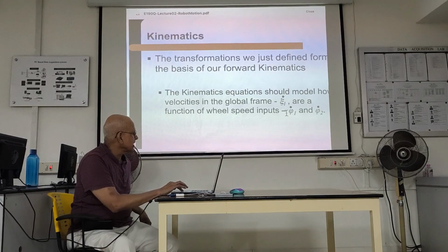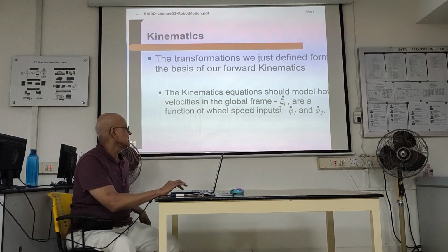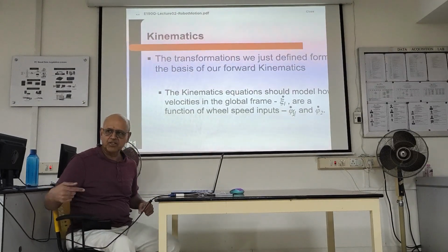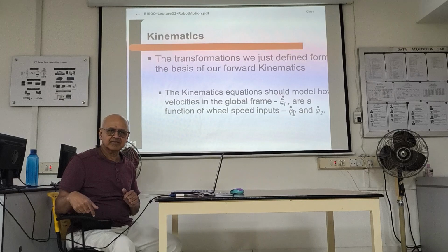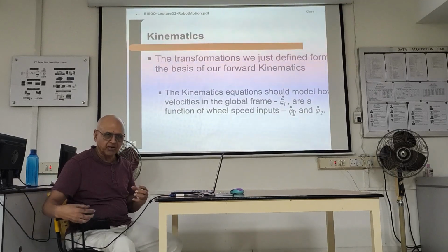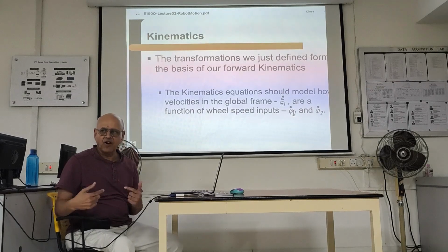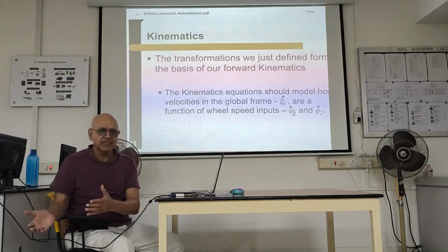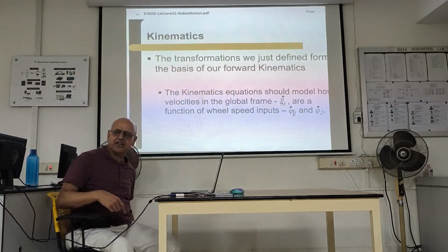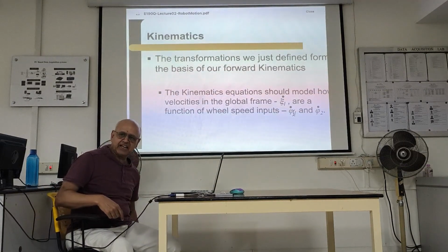So this is not a minus sign, by the way, it's just a dash. So phi 1 dot is the rotation of the right wheel. A motor can directly control that. Phi 1 dot is the rotation rate, radians per second. So if you connect a motor there, it's going to spin it, right? So what is the fastest speed? You have to ask, what are the motor specifications? So it's directly related. Same thing with the left wheel. The motor is directly connected here.